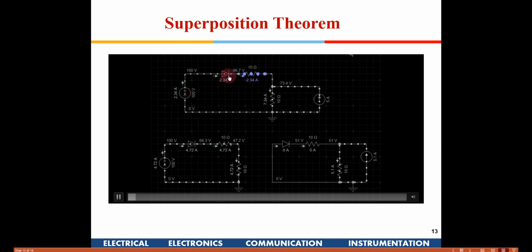That will ensure that this diode is forward biased, so this loop is activated. You will find some current. There is a current source here that is also pushing in some current. So you have a total of 7.3 ampere flowing into this 10 ohms resistor. There is current coming from here and current coming from here, both.